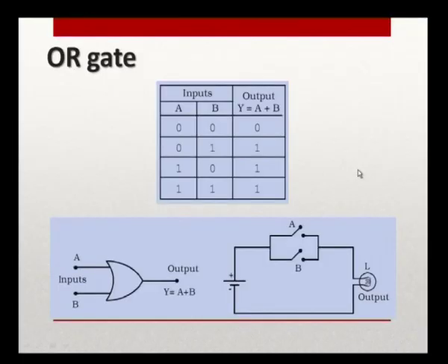If we keep on varying the inputs, how many such combinational inputs could we give? By permutation, it is 2 to the power 3. There are 2 values possible, 0 and 1, for the 3 terminals A, B, C. So it is 2 to the power 3, which is 8. So 8 combinational inputs we could give for a 3 terminal OR gate.